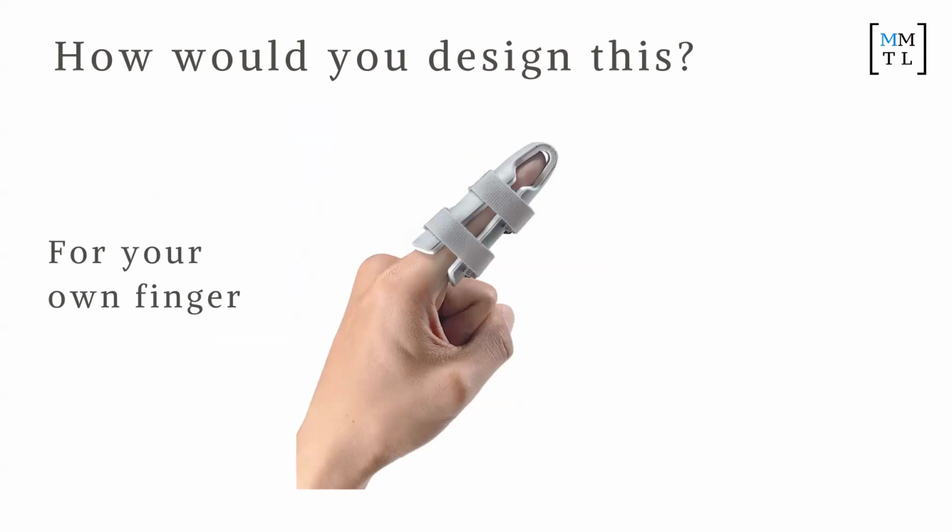How would you make this? Yeah, you could just use mirror. For that, you just make one half, extrude, mirror. Yeah, or mirrors. I would do that.